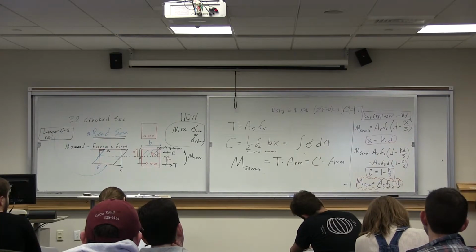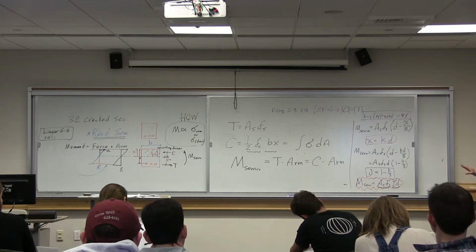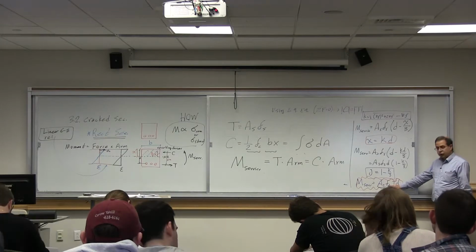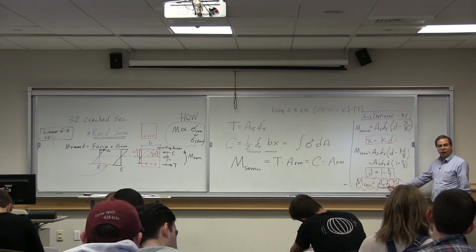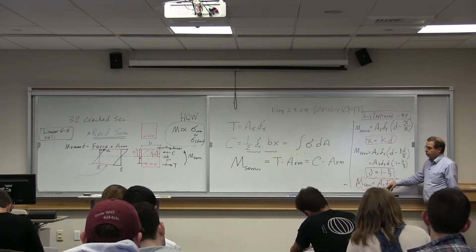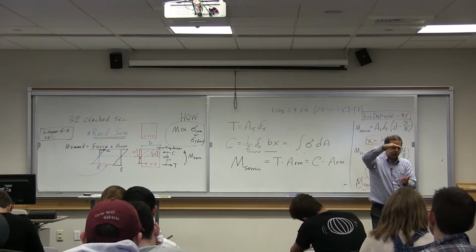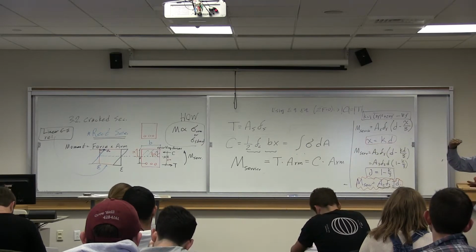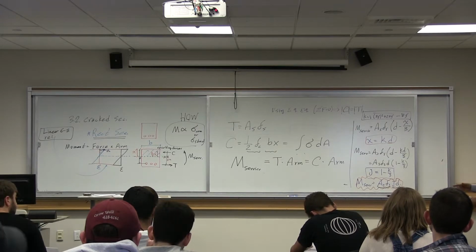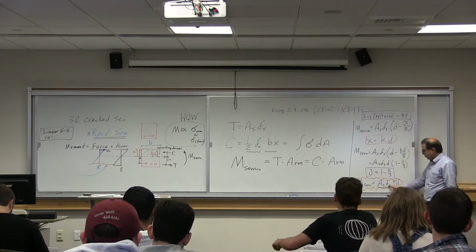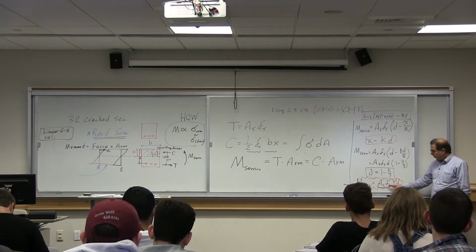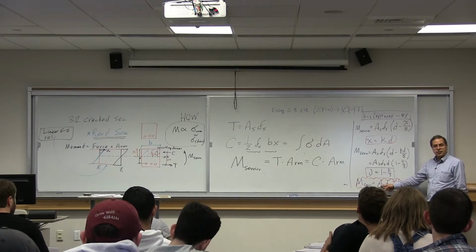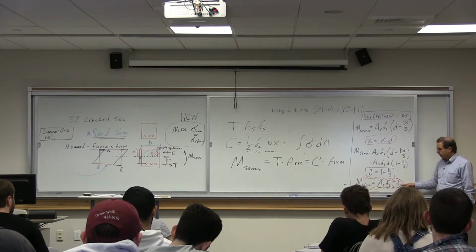I'll finalize our discussion here with this statement when we take a 5-minute break. Let's say you want to limit the stress in a section to 1/2 of Fy. Going back to that bridge case, you have a cross section, you want to know the maximum load that could be applied to the bridge. You look at the cross section, you say if I want to limit Fs to 1/2 of Fy, I replace this with 1/2 of Fy, multiplied by As, get the force, multiplied by jd, get the moment.